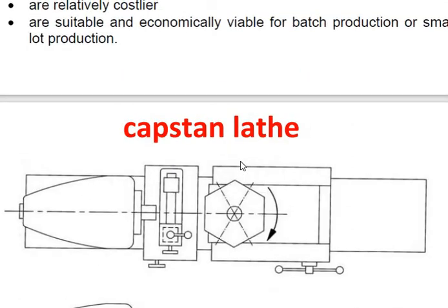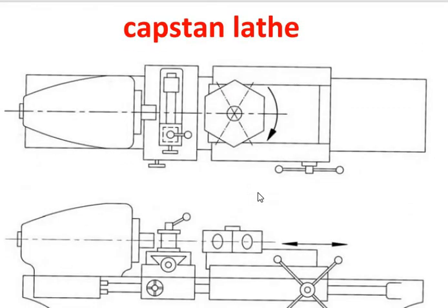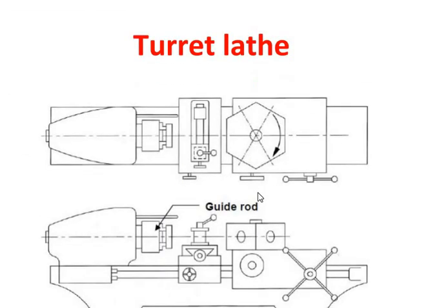In the capstan lathe, the turret travels with a limited stroke length within a saddle type guide block called the auxiliary bed, which is clamped on the main bed, whereas in the turret lathe the heavy turret is mounted on a saddle, which directly slides with a larger stroke length on the main bed as shown in the figure.